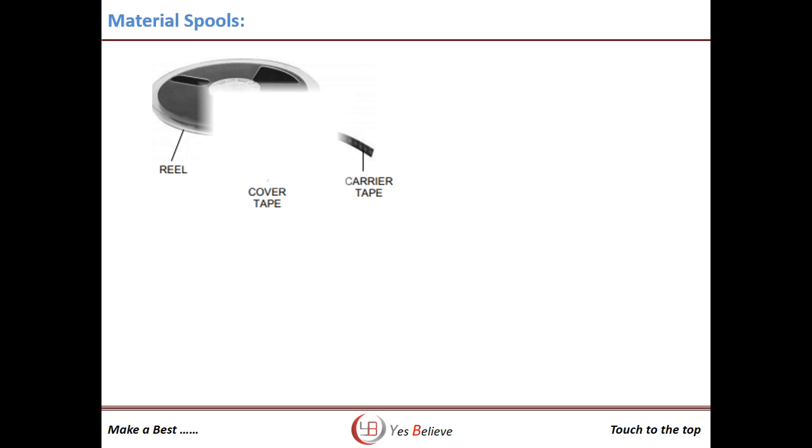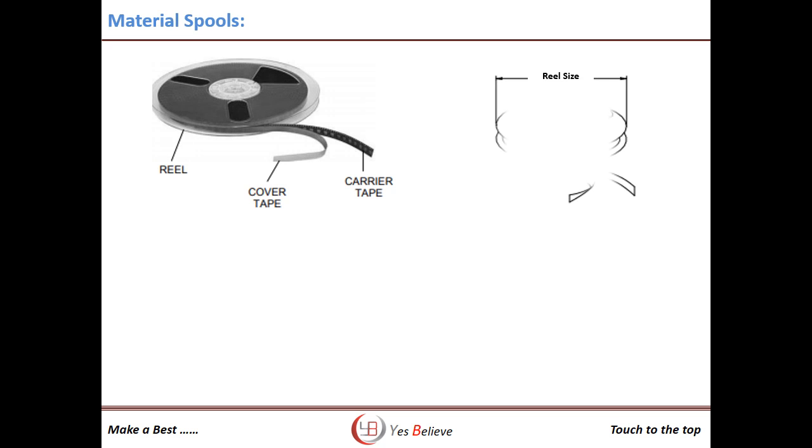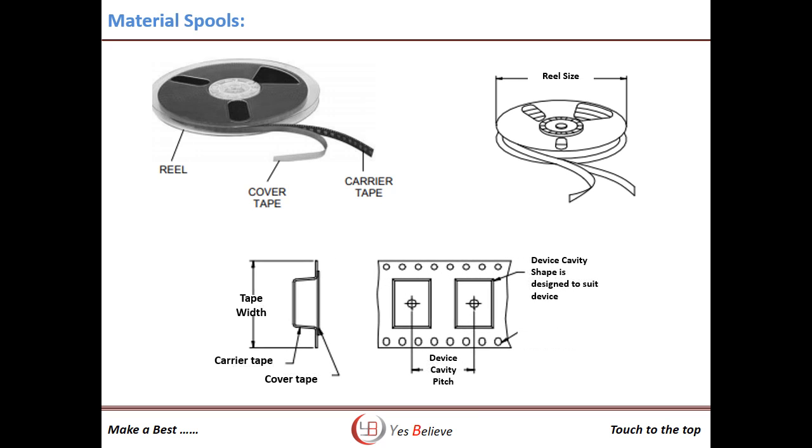Automation of surface mount assembly by the use of pick and place machines to handle tiny components has been enhanced by evolutionary improvement in tape and reel systems, which can accommodate as many as 4000 parts on a 13-inch reel. This results in less frequent component reloading and less downtime of the assembly equipment. Other advantages of tape feeders include versatility, or the ability to handle a variety of parts.